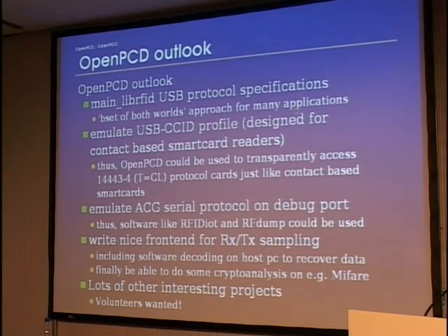And then another to-do is writing a nice front-end for the RX and TX sampling, the bit banging for SSC that Milosch has been talking about. Stuff like host software to recover the data and to do host-based analysis of the bit stream. And this would really get us way further in enabling people to do cryptanalysis on MIFARE Classic, for example. And there's lots of other interesting projects, and volunteers are always wanted.